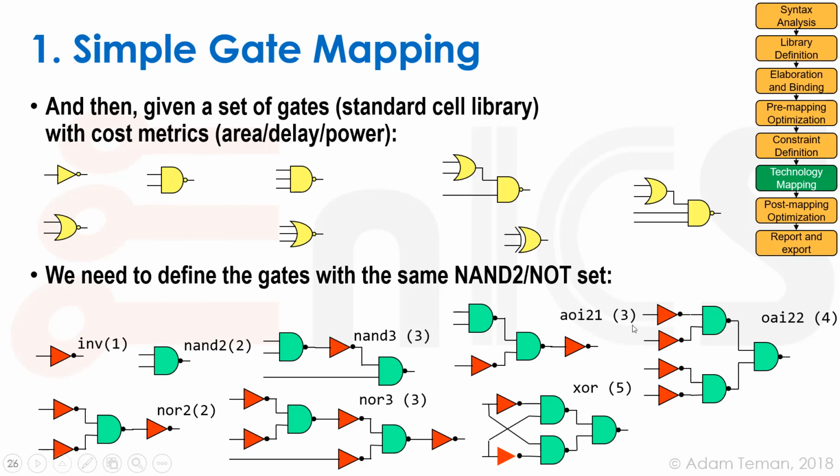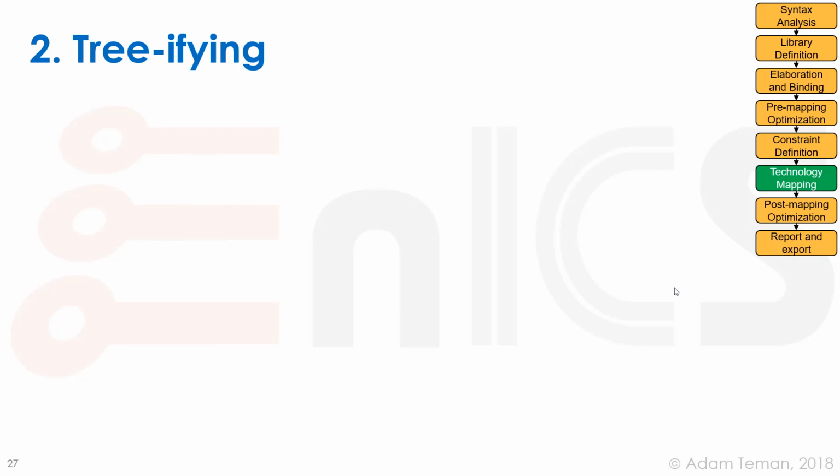Again, how we give these costs is actually an art, and it's not something that's optimal. It's done according to all kinds of heuristics and decisions. Maybe how we characterized our lib files depends on size, maybe on power, etc. So these are just numbers that I'm giving as an example. They're not something that is straightforwardly calculated. So remember, in our tree covering algorithm, the cost of each gate is an important input, and it can lead to lack of optimality. So that was simplifying the netlist.